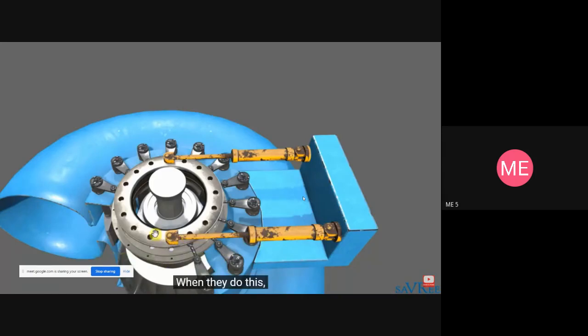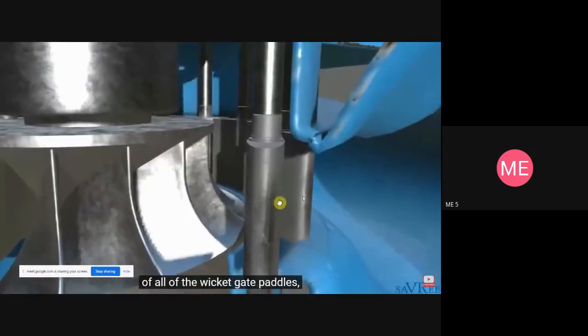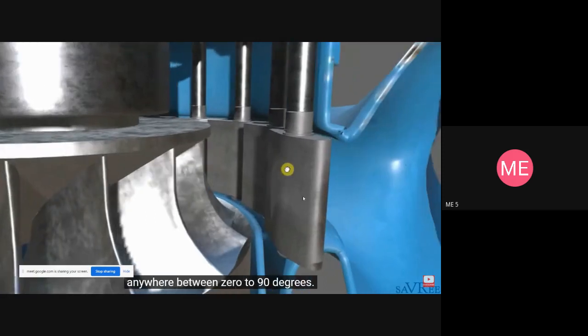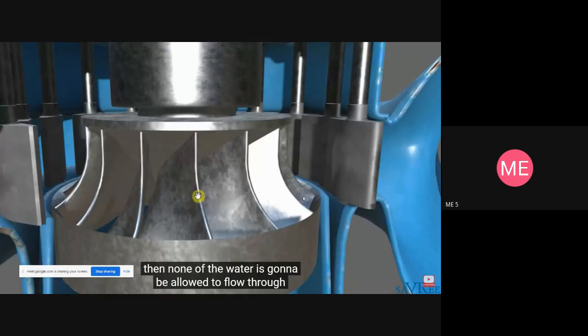When they do this, they're actually going to turn this entire assembly here, and that is going to rotate the position of all of the wicket gate paddles. So all of these pieces here are going to rotate anywhere between 0 to 90 degrees. If the wicket gate is fully open, then the water is allowed simply to flow through and go directly to the runner. If the wicket gate is fully closed, then none of the water is going to be allowed to flow through and get to the runner.